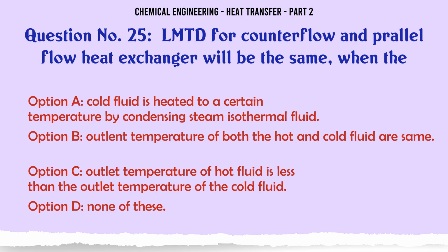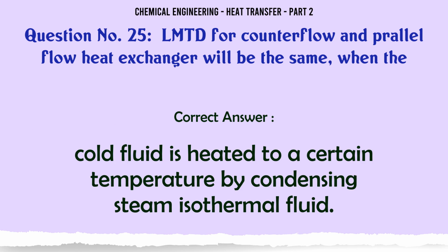LMTD for counterflow and parallel flow heat exchangers will be the same when the A. cold fluid is heated to a certain temperature by condensing steam (isothermal fluid), B. outlet temperature of both the hot and cold fluid are the same, C. outlet temperature of hot fluid is less than the outlet temperature of the cold fluid, D. none of these. The correct answer is: cold fluid is heated to a certain temperature by condensing steam (isothermal fluid).